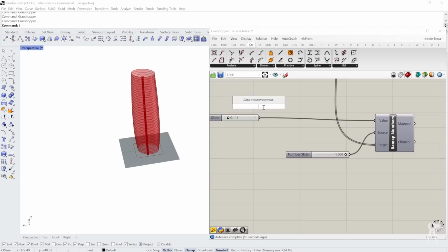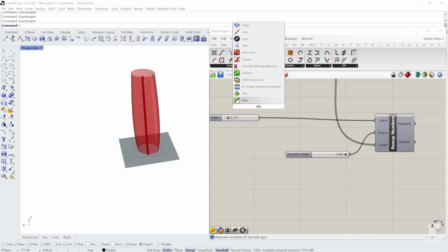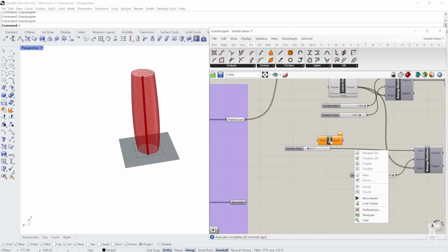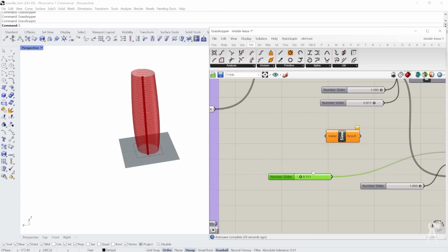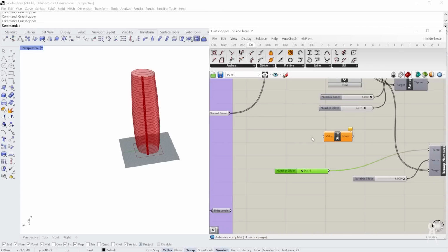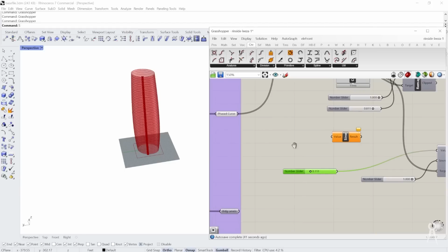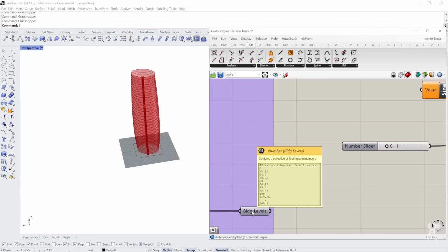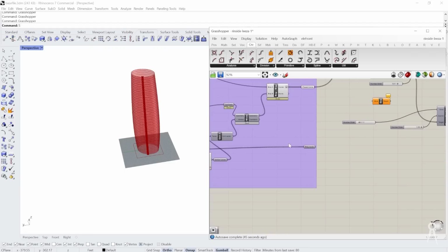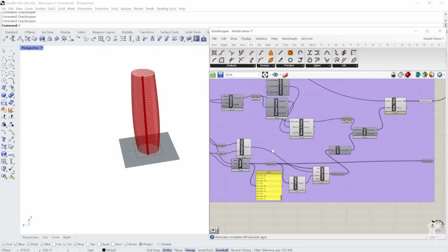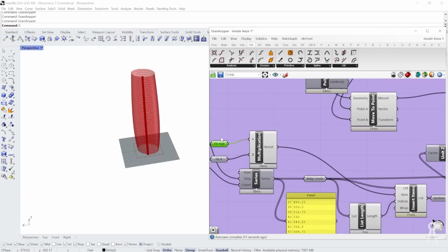And the sine wave is actually going to connect to the levels. We'll put the sine function in. That's from the math tab, right? And we want to really be doing the values from 0 to 90, because we're not doing the sine wave below, we're just doing the sine wave above 0 to, and it's actually 0 to 180, okay? So that 0 to 180 is what we're going to get, and we're actually not going to use the building levels. We're actually going to use directly our function that's telling us the floor numbers, right?